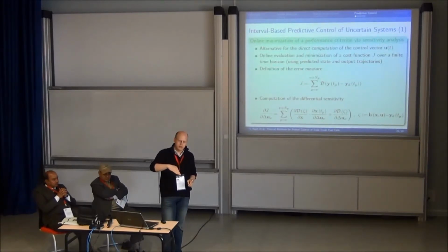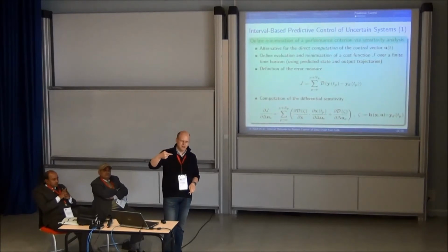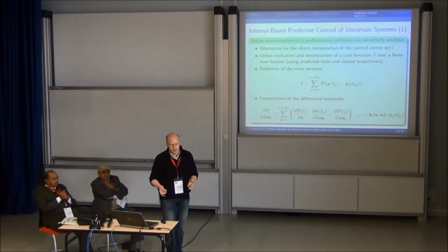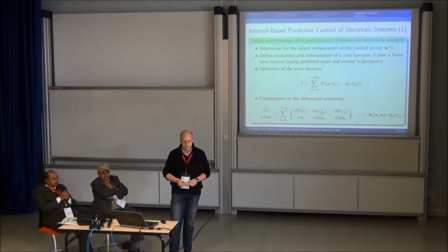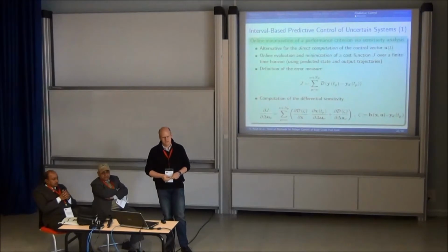The optimization procedure that is used in this bisectioning scheme that I have in this sliding mode control strategy is really searching on interval boxes, and it's taking out the interval box that has the smallest supremum. And there we use directly in the optimization also the intervals. As you said, you know exactly what the computation time is that I can spend, and afterwards I just stop.